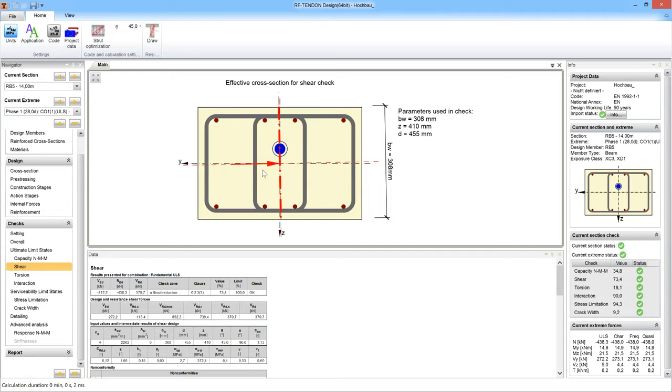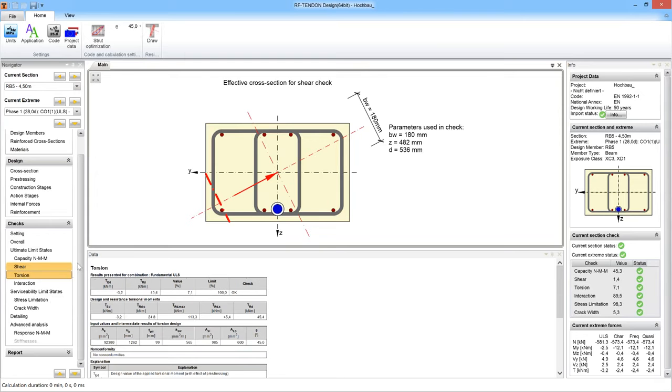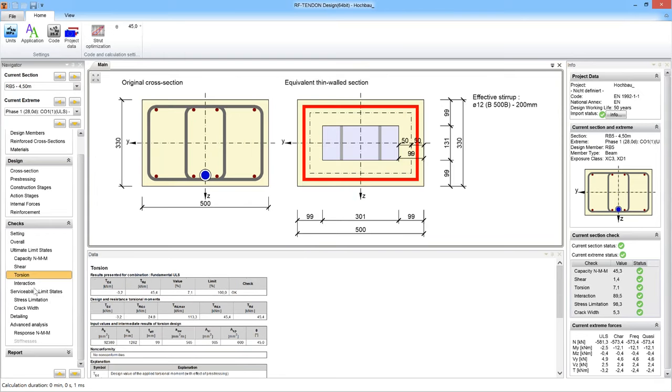If we apply a high normal force of pre-stressing, then of course just behind the anchor we should not use the sectional analysis. This is the anchorage zone, but I don't think I made it immediately after the anchor, and still RFEM integrates quite significant forces, but we can design them with no problem. So let's go back to the midspan. Maybe I should have shown this torsion above the support, but it doesn't matter.